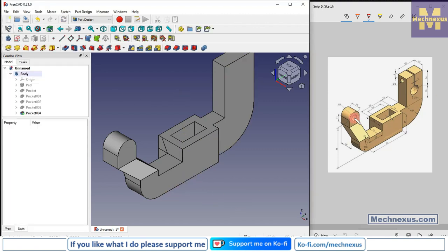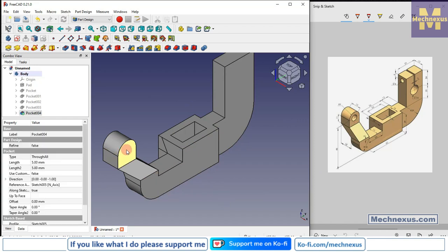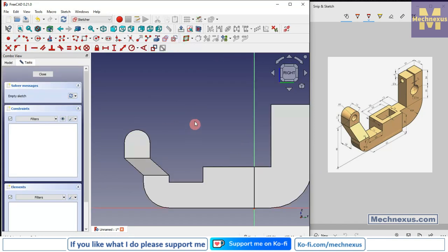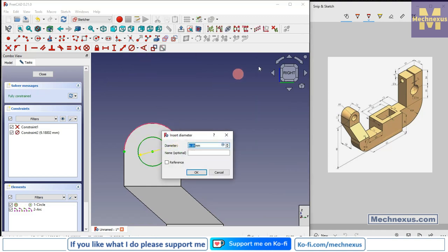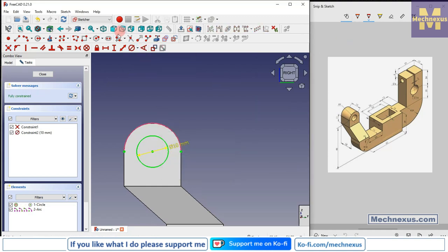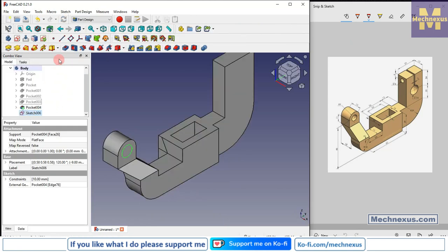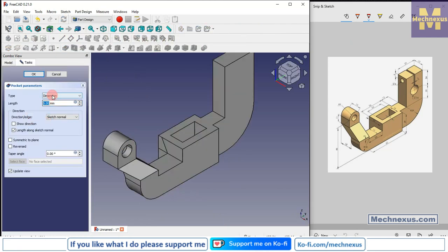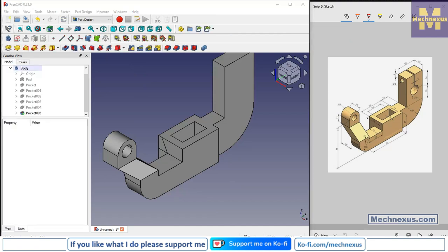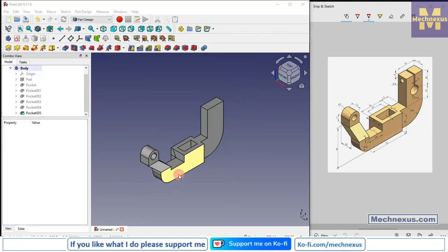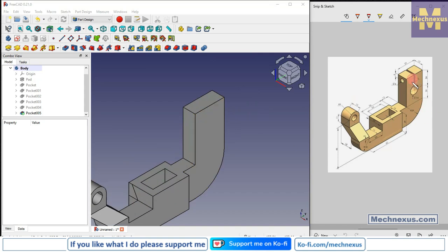Now we will create this hole. So for this we will select the face and click on the sketch, click on the project geometry, select circle, create a circle, and select diameter and provide 10 mm of the diameter, and click on cut, and from here say through all, say OK. Now we will create this cut.